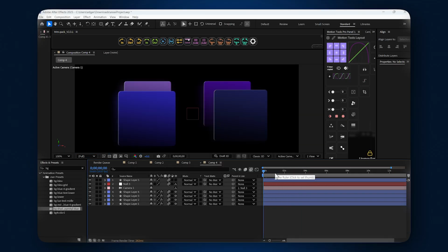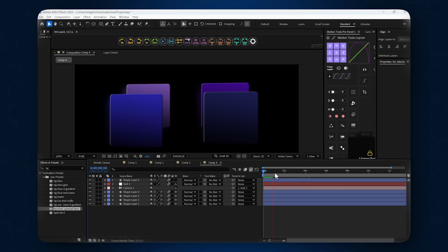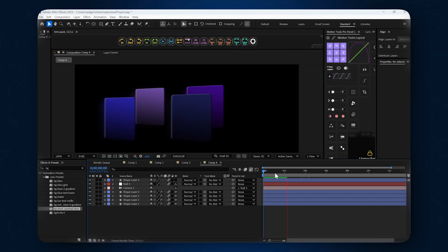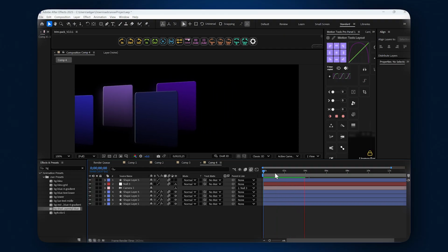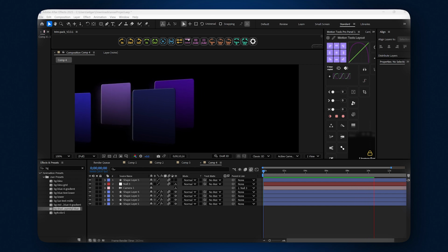Smart focus tricks. Use the preset expressions under Layer, Camera. Link focus to point of interest equals camera always focuses on its target. Link focus distance to layer equals camera automatically focuses on any object you choose.